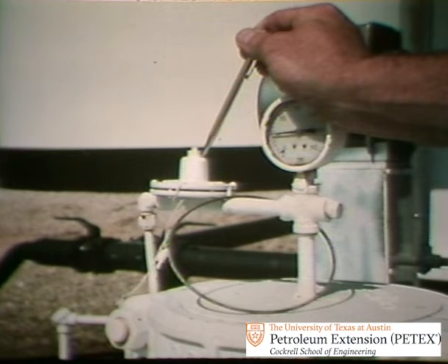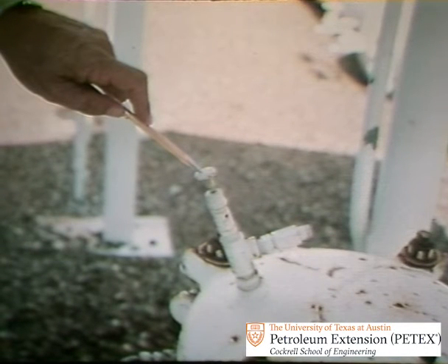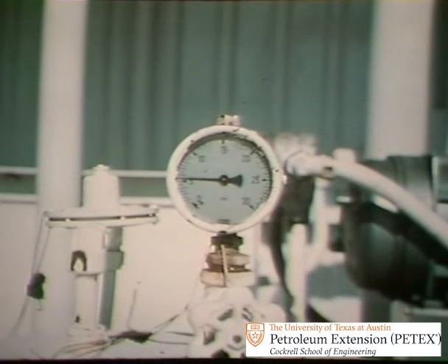A pressure relief valve should be included to maintain enough pressure in the receiver to minimize evaporation loss. Normally, it's set at about 10 psi, but don't set it so high that the sample can't enter the receiver. A vacuum breaker allows you to drain the receiver while it's closed. The breaker provides a vent to the atmosphere that breaks the vacuum inside the sealed receiver. A pressure gauge is required on receivers to indicate that all openings are properly sealed and the pressure relief valve is working properly.